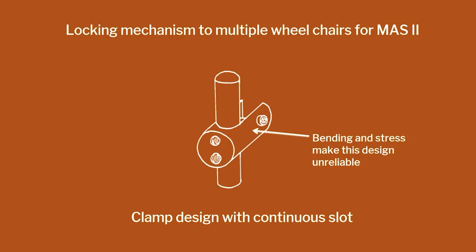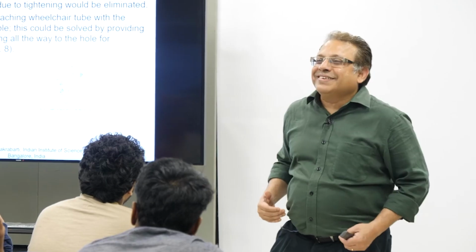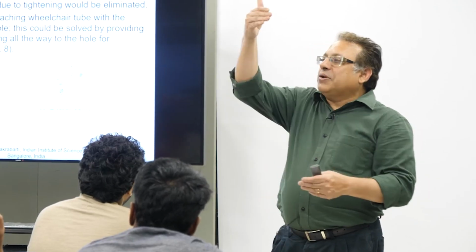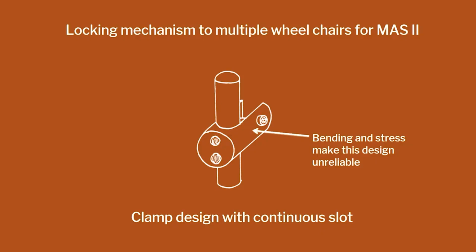And one way to deal with this is that we are going to have this whole thing as a single part. The problem is happening because there are two parts, and we have to keep these two planes on the same plane. Can I make the whole thing a single plane? Because it's a single part, I can attach the actuator assembly to that and the plane, and the assembly can come from one side. It's a continuous slot, so I can push it in, and it's slightly bigger in size, and then I can have the screw to tighten it.